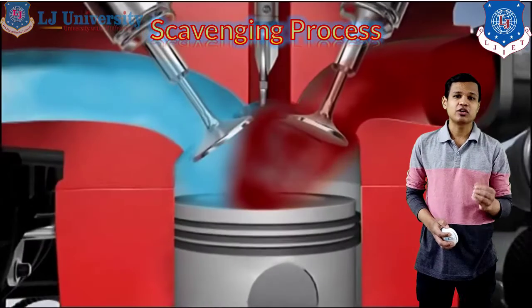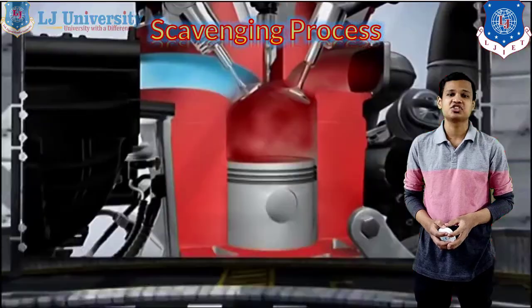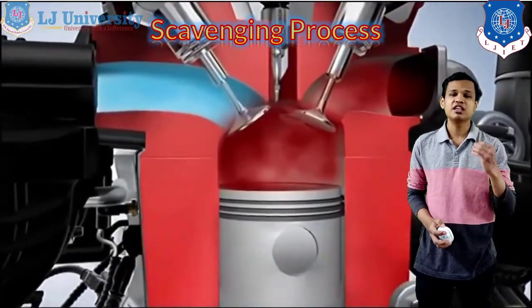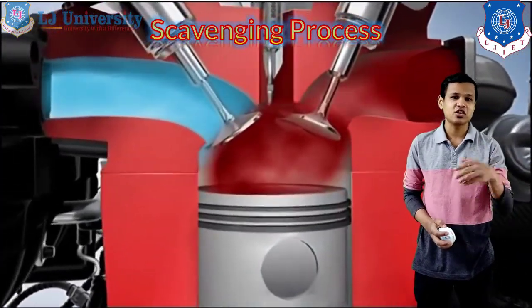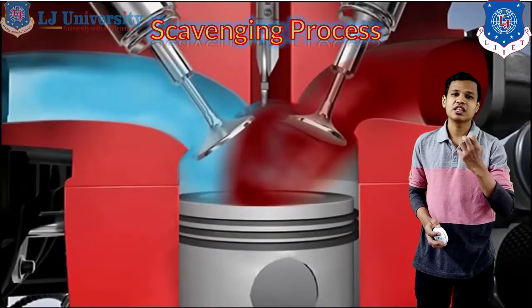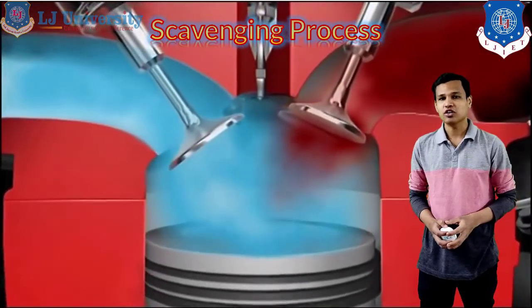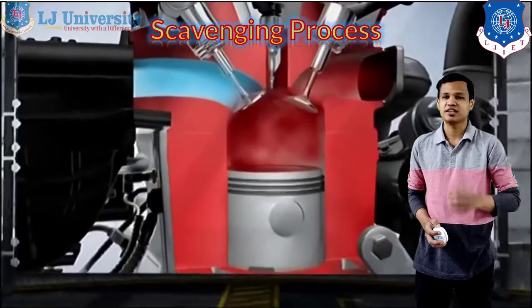So if our petrol is exhausted with the exhaust gases generated in the engine, then we will lose petrol that is not even burned. We have not used its energy. So overall the mileage of the engine will reduce if we are not providing the scavenging process in a petrol engine.